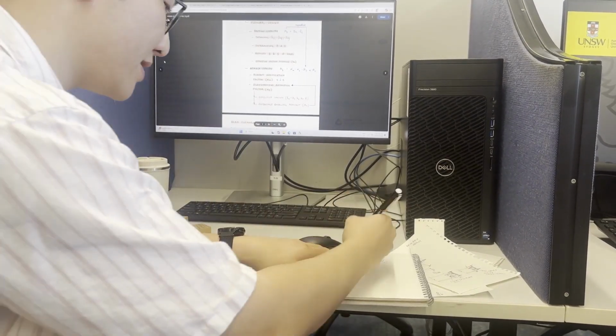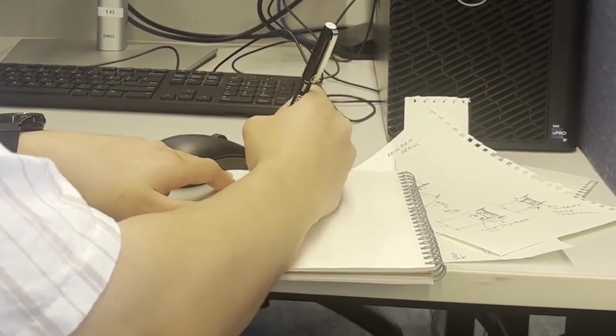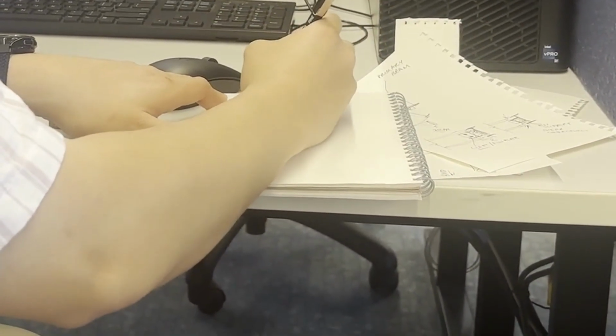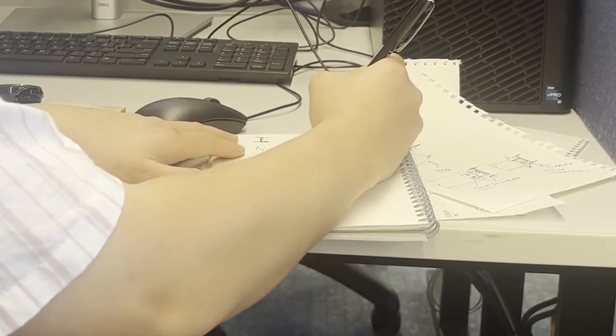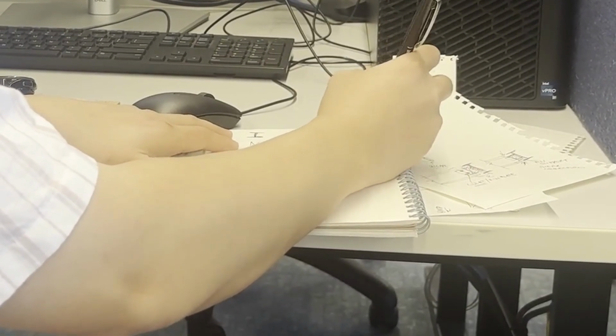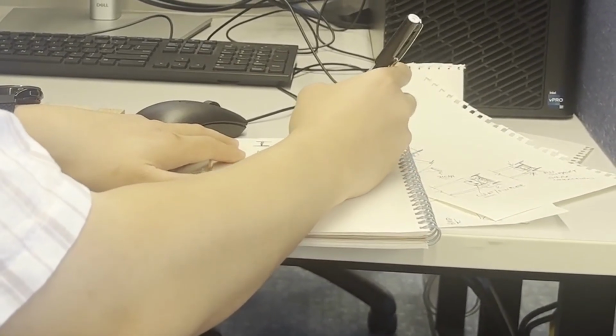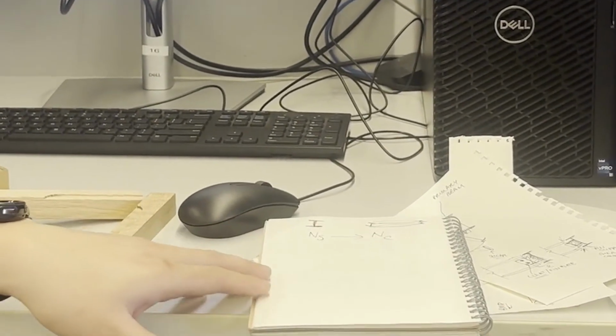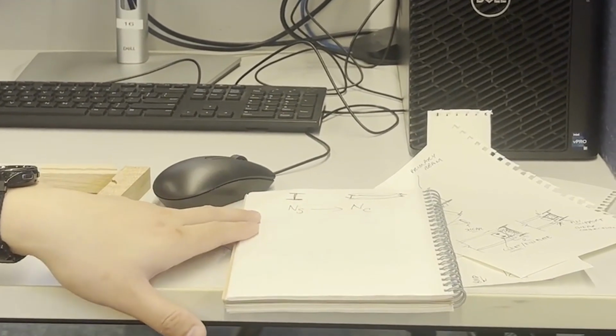Okay? So that's your section, let's say it's an I-beam, and you're trying to work out how strong it is, right? After you account for local buckling and stuff. And then for the global capacity, or the member capacity, you're trying to work out its strength after buckling and stuff occurs, okay? That's axial buckling.